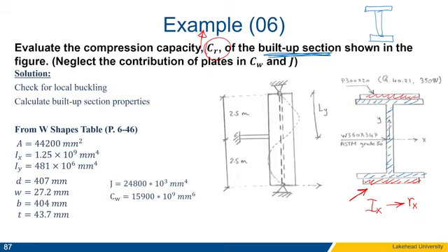One of the other advantages: sometimes the flange does not satisfy table 1, so it will exhibit local buckling. One way of fixing that, or either for the web, by the way, but in our case we added plates to the flange, we can actually put 2 plates like that. When we add those plates either to the flange or to the web, they will prevent the buckling of the flange because they are welded to it.